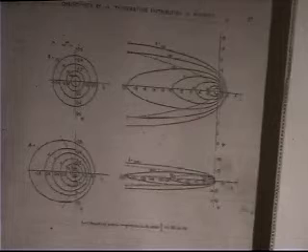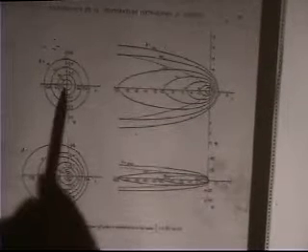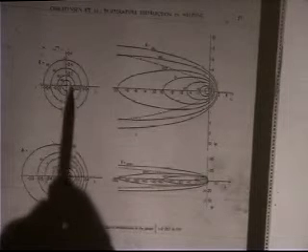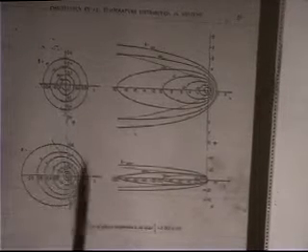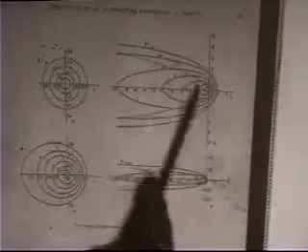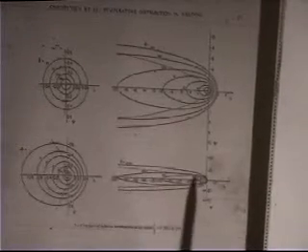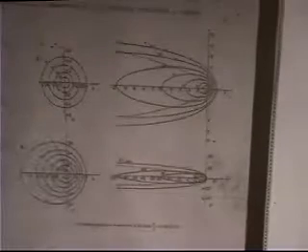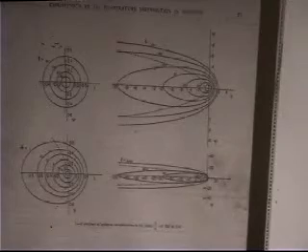This parameter n, which is what Christensen called the operating parameter, is a measure. It contains a number of things. You can look at the paper if you're really interested. If I'm traveling very, very slow, then basically the travel speed, this whole thing looks nearly symmetric. If I travel a little faster, this thing gets distorted. I travel faster still, I get isotherms that look like this. If I start traveling at the speed of lasers and electron beams, I get things that look like this. So from this, I can look at what distance the heat travels out to the side and whatnot.